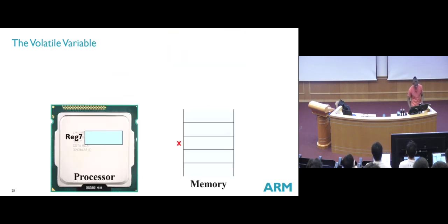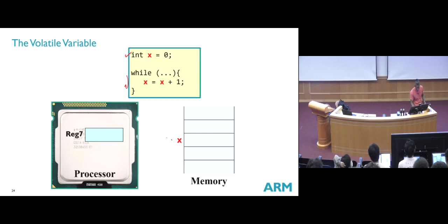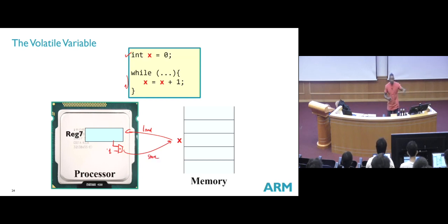So what happens is I will need to do a load operation from memory to my internal register. After I do that, I pass this to my ALU. Then I say I want to add with a 1, correct? After add with a 1, then I must do a store. So every time I run this loop, by right I should do this. But